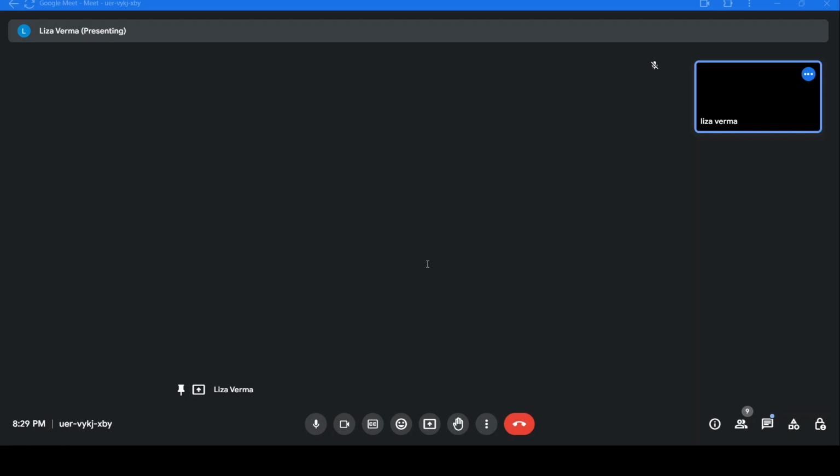So assume my main program starts at location 8000. If I have RST 0 in my program, then it will jump to the 0th location, the corresponding address for reset 0. I can do nothing, like I can have 2 or 3 NOPs, and then I can have a return instruction, and I can return from there to my main program.